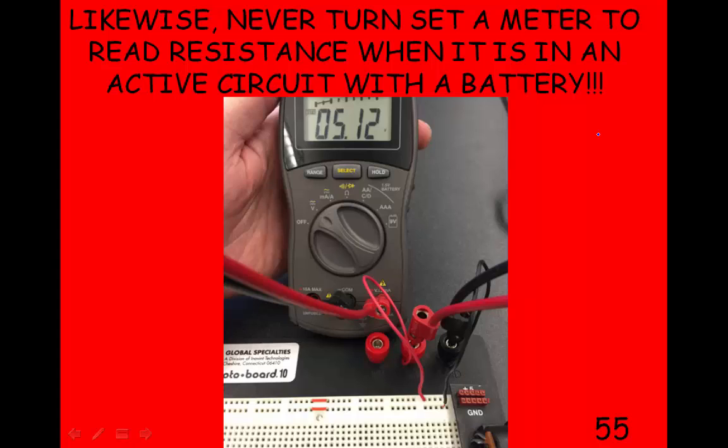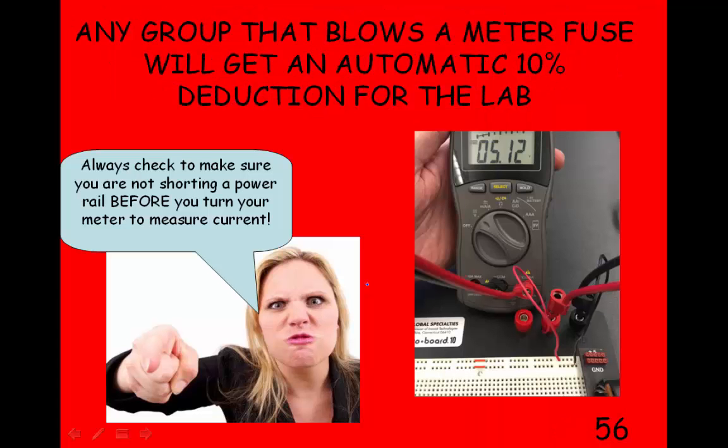And finally, never set a meter to read resistance. If you wanted to read the internal resistance of your power supply, and you just set this to ohms, well, you can't do that, because the meter works by putting out its own voltage onto the voltage of your supply, and they're fighting each other. It's not going to like it, and it could also break your meter. So don't do that. Always check that you're not shorting the power supply before you turn the meter to measure current, or before you turn it to measure ohms, make sure that there's no battery in the circuit.